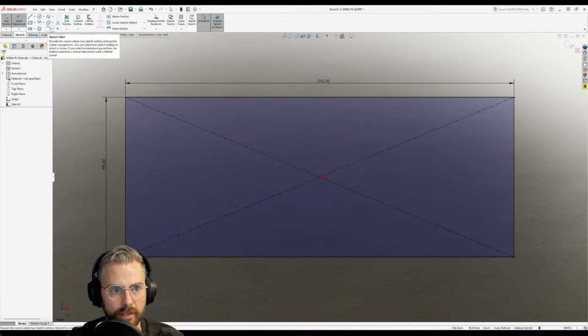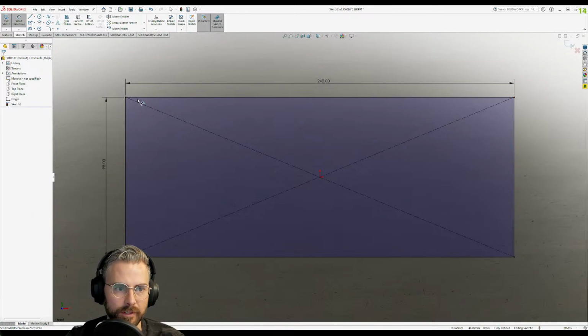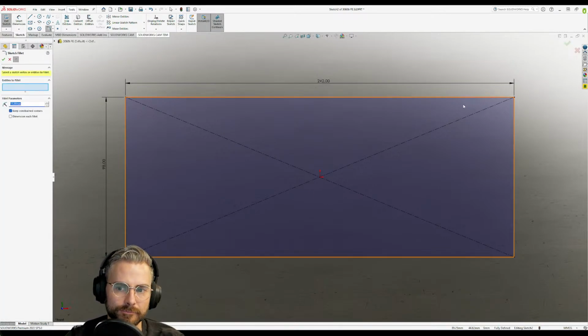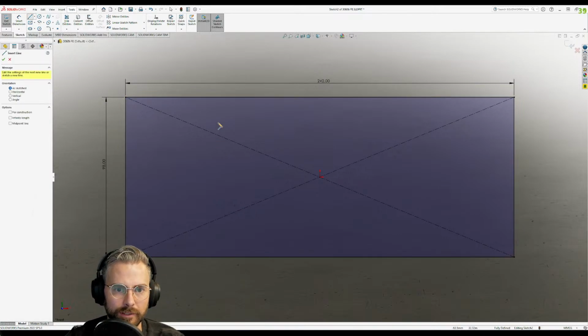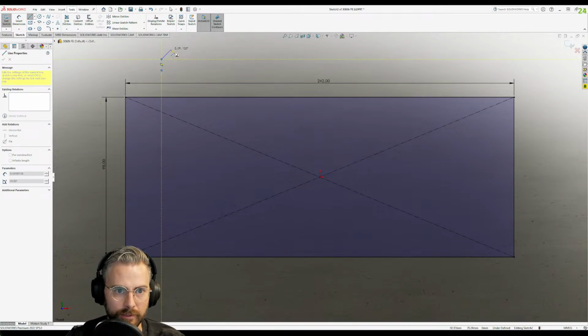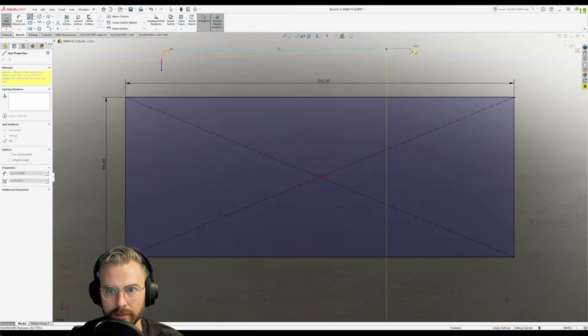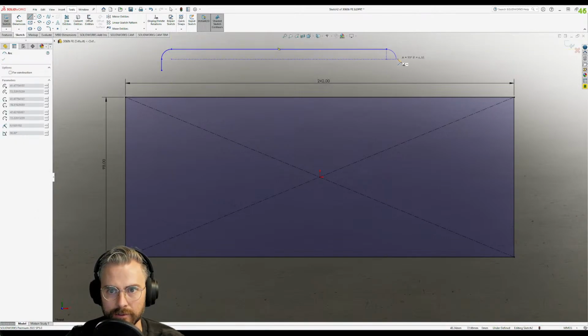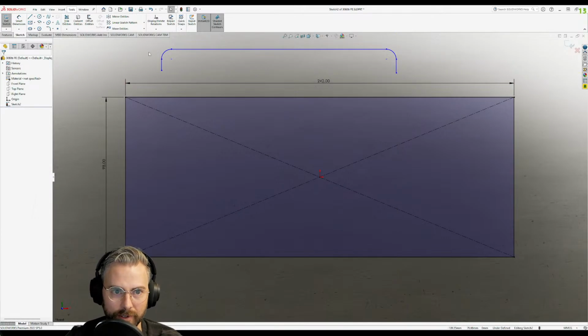So sketch fillet. We've already got our dimensions, but they're going to the ends of these straight lines. If you add a fillet in there, you could draw a line, click, you have a line, you touch the point again, and then it makes it a radius. Click, click, touch that line again, you make a radius. You could do something like that with our rectangle.